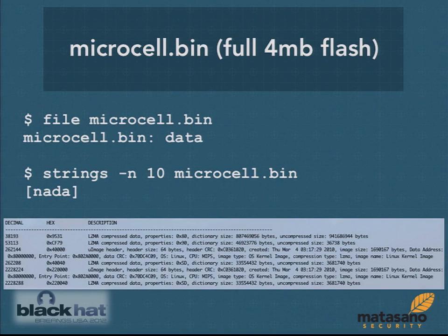So the first thing that I did with the full 4 megabyte flash was run file, and it didn't give me anything. Strings didn't give me anything either. However, when running binwalk on it, you can see that representation at the bottom.